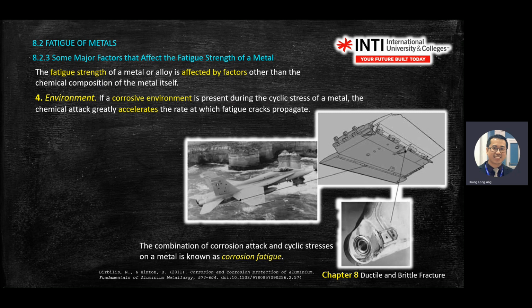The one that you see here is a damage happened on the fighter jets. Because in the operation, normally they fly into those open seas, especially those Korea, the big mothership. The seawater, the vapor will have some damage to the hinge here. There's a hinge over here. So this hinge will more easily crack.